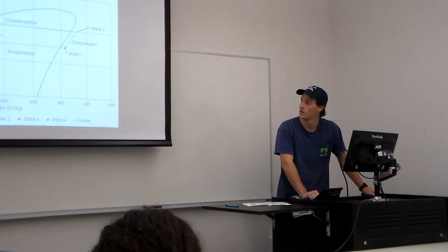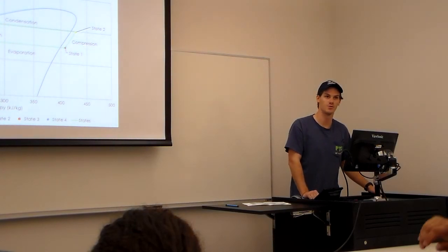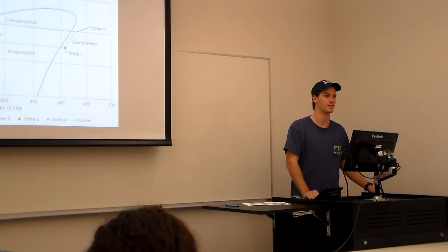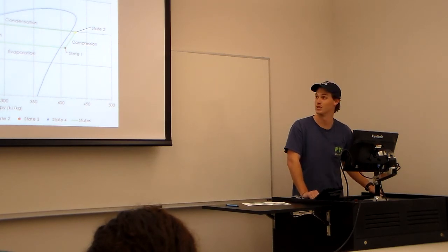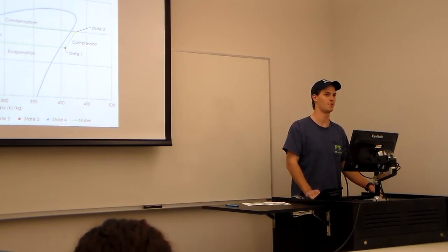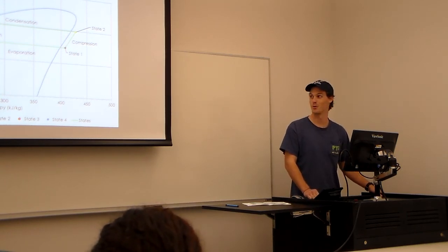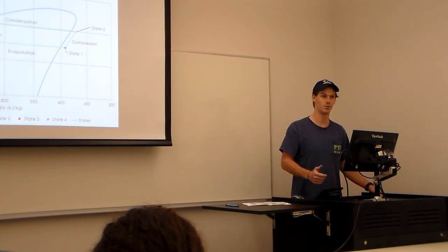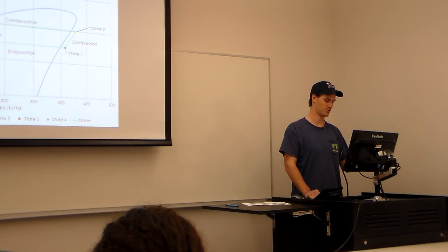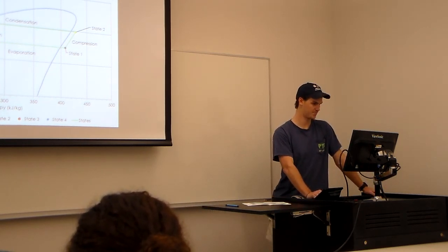Another note here, the data given to us in the steam tables in the back of the lab manual was quite a bit different than the data given in the back of the thermo textbook. Like at 0 degrees C, our enthalpy according to the lab manual was 50.2 kilojoules per kilogram, and in the back of the thermo book, it's like 200 kilojoules per kilogram. So I went with what I was comfortable with, which was the back of the thermo textbook, and pulled it all into Excel and made these plots.